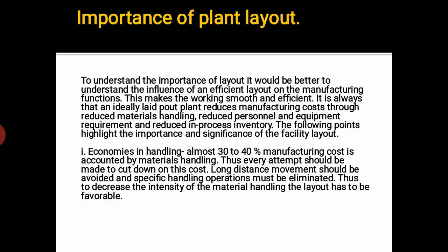Here we are going to see the importance with the help of different points. Let us see it. To understand the importance of layout, it would be better to understand the influence of an efficient layout on manufacturing function. This makes the working smooth and efficient. An ideally laid out plant reduces manufacturing cost through reduced material handling, reduced personnel and equipment, and reduced in-process inventory, and the following points highlight the importance.